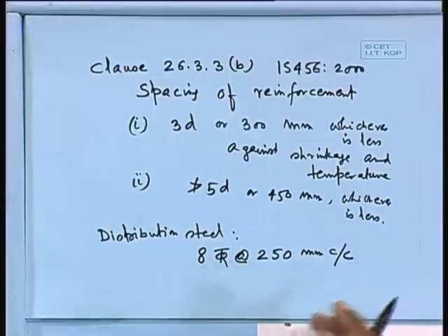Now, finally, we have to show the detailing. For reinforced concrete structures, we have to show the detailing. That means, for beams we have to provide the longitudinal section and also the cross section. In the longitudinal section you have to provide the curtailment of the reinforcement and the steel spacing, all those things will come, and your cross section will show a typical cross section. That means, at which section you are taking along the longitudinal one, that you have to provide. Here also for the slab, we have to provide the reinforcement detailing.